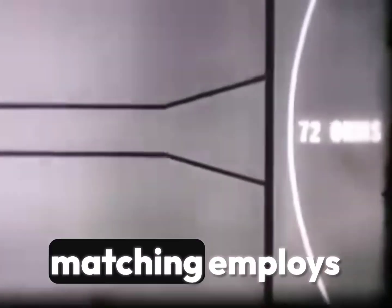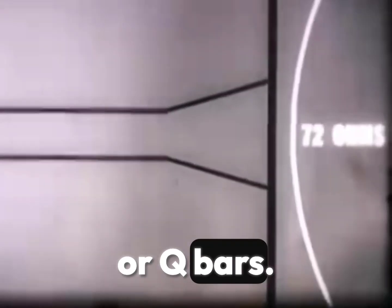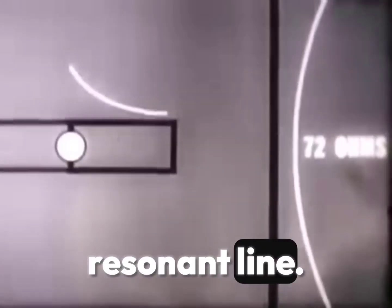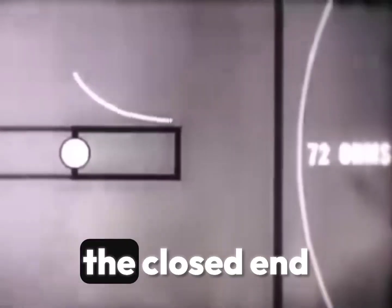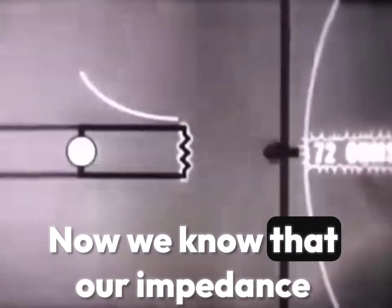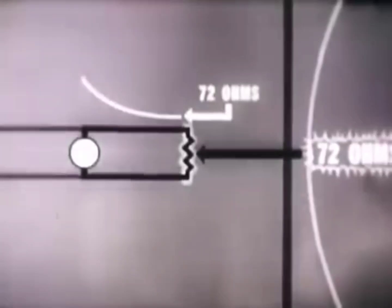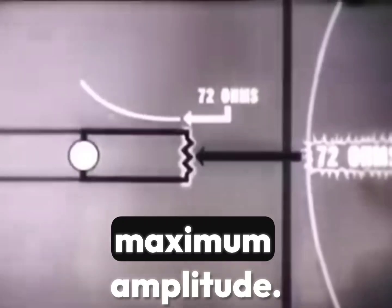Another method of impedance matching employs two lengths of metal tubing called a quarter-wave matching transformer, or Q-bars. These tubes are merely the twin wires of our old friend, the quarter-wavelength resonant line. In this simple closed line, the impedance curve is minimum at the closed end and maximum at the other. Now, supposing we put a resistor in the closed end of the line, say 72 ohms. Now we know that our impedance value at this point is 72 ohms. This changes our curve a bit, decreasing the impedance value at the generator end of the line because the standing wave is no longer at maximum amplitude.